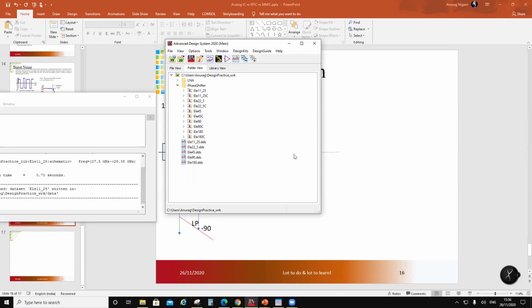So according to me, for another small element, you need not put a high pass, low pass, or band pass element. You can just use the length of the line, because the angle has gone so low that the error you accumulate across the band is not going to hurt you.